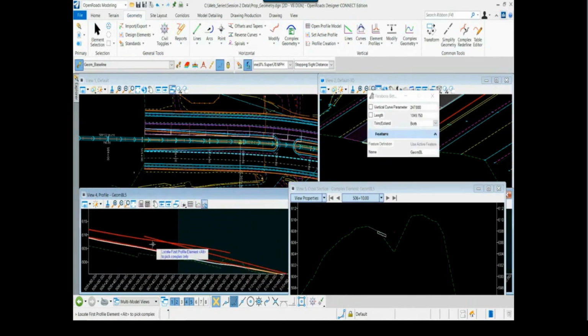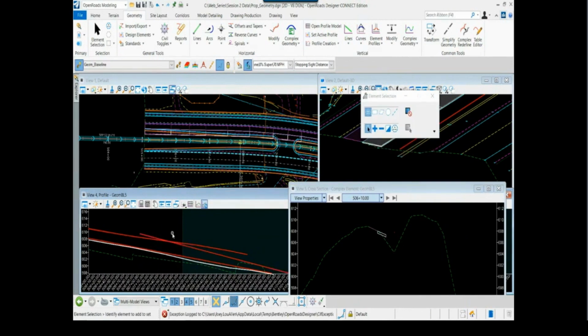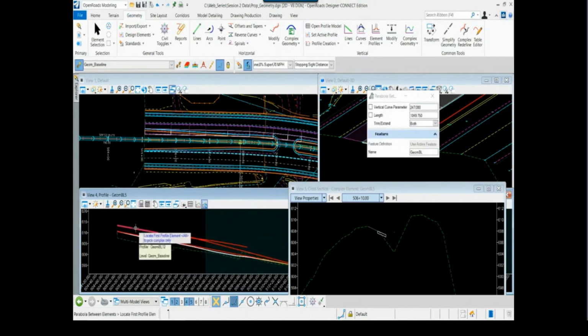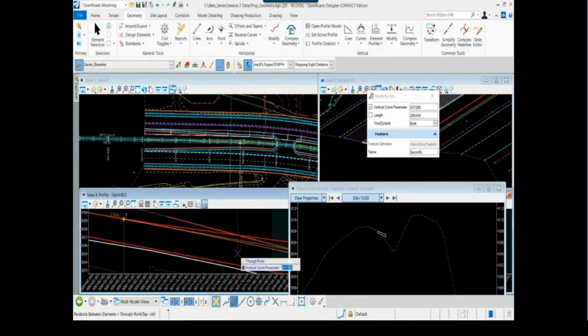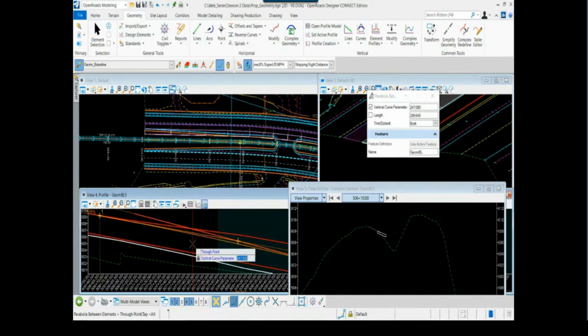So as I zoom in, bear with me, I'll select each of those elements. Let me select each element. Let's back out, make sure I've got there. I want to be sure and select the geometric element and place that arc. Be sure you select the geometry that you created, not the graphical representation of the pavement. Now at this point, my K value is at 247. It's locked based off the design standard I have placed, or I have told it. So I'll data point through the prompts, and now I have that vertical control line in place.